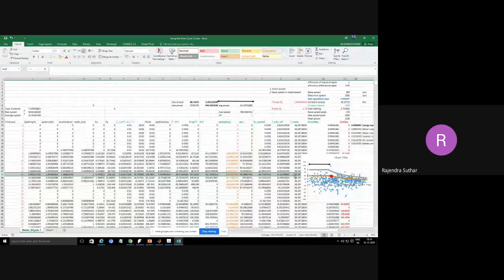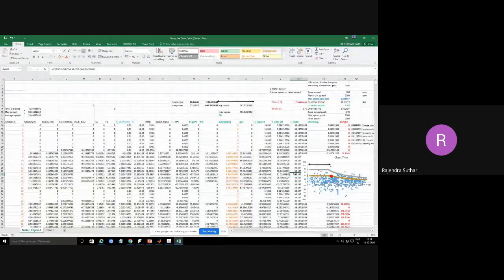And so we need this much amount of torque. Sorry, the data is 51. So the torque requirement corresponding to this 6 kmph, with gear ratio 1, and for the defined motor or vehicle configuration, we need this much amount of torque.